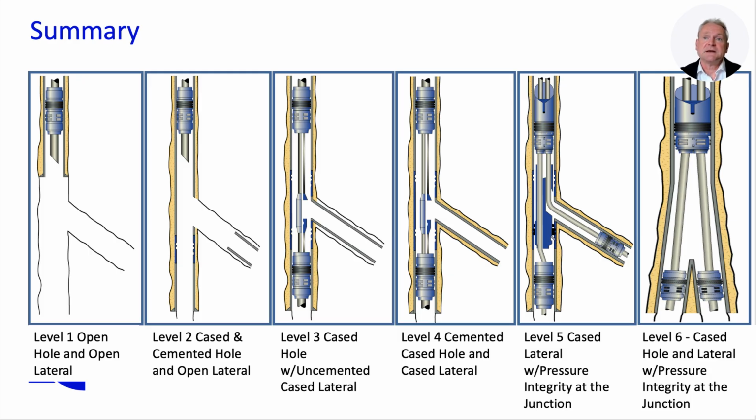However, it has significant limitations. Lateral access is minimal, intervention is nearly impossible, and there is no control over inflow. Essentially, it provides reservoir contact, but with little long-term flexibility.